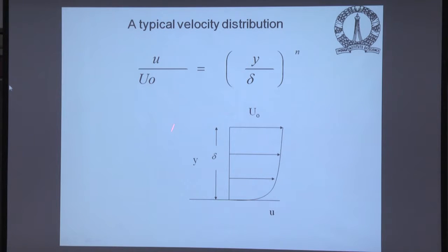But the trouble, however, is that this velocity profile is not good enough for many practical things. For instance, why would you be interested in these descriptions at all? You would want to be able to find out the shear stress at the wall, if I want to know the drag, right? Or heat transfer, for instance. For considerations like that, you are interested in the slope at the wall. If I try doing the slope at the wall with this, clearly I have a problem. There will be a singularity. So this is not good enough.